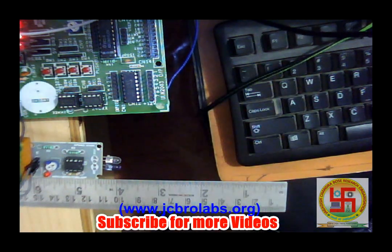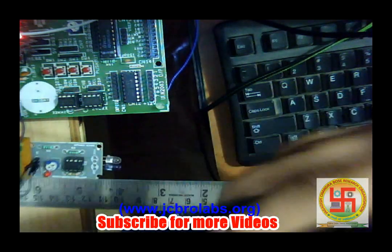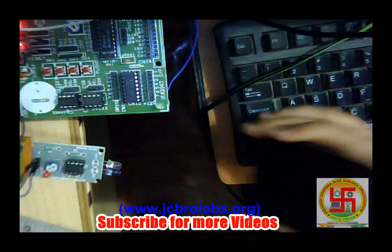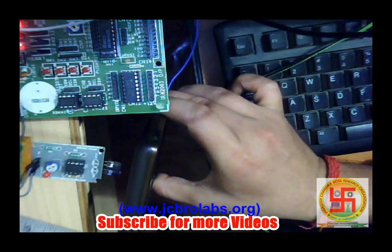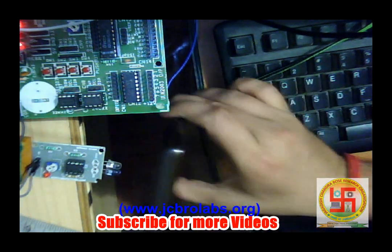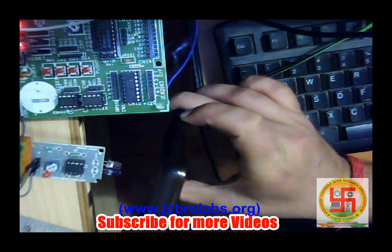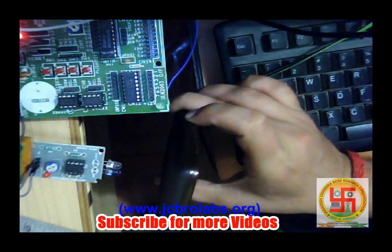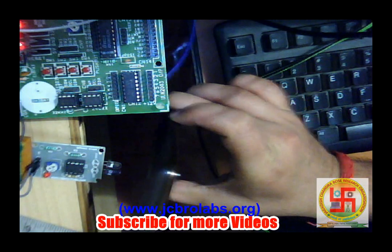Now if the range is different, let's try with this phone which has this black color, and let's see whether it is able to detect it or not. Okay, oh no, it's not detecting it. So this IR sensor is not detecting this black surface because all the IR light which is being emitted from the LED has been absorbed by the black surface and it has not been detected.